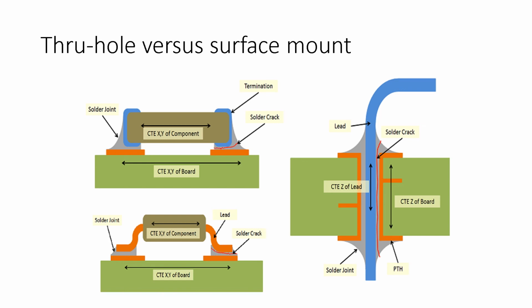If we look directly underneath of that, this is another type of package where they have legs, but the legs are flattened at the bottom of them. And that allows for a really nice solder joint contact there. So you get some solder in between the two of those, and that makes sure that you have enough surface area with contact to the solder joint that you get a nice mechanical connection there.